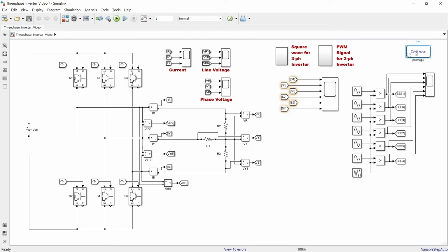In other words, it simply stores the equivalent circuit of the prepared Simulink model in equation form. Right, so make it clear in your mind that the role of this powergui block is to store all this simulation in equation form, do all the processing and then give us a visual result. So this is the role of this GUI block in our simulation.